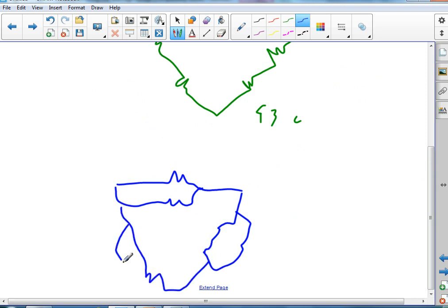Now, why would I care that I was Y or delta connected? Because you got one phase that's going to be basically a grounding phase, and you got two other phases that are your 480. You can get 480 from phase to phase, but if you take the phase to ground, you basically get like 0 volts.